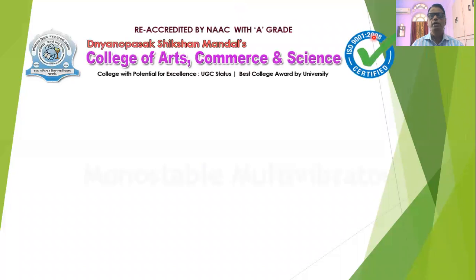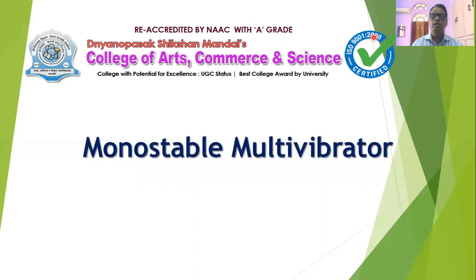Hello friends, welcome to the session on multivibrators. In this session, we'll be discussing monostable multivibrator. We will see the circuit diagram and working of monostable multivibrator. We will also analyze the circuit in order to obtain an expression for the gate width of monostable multivibrator.